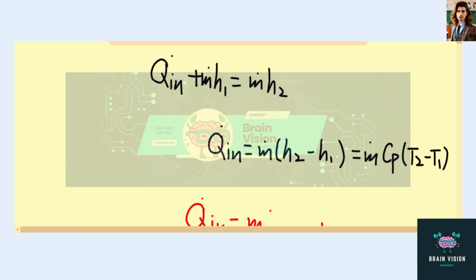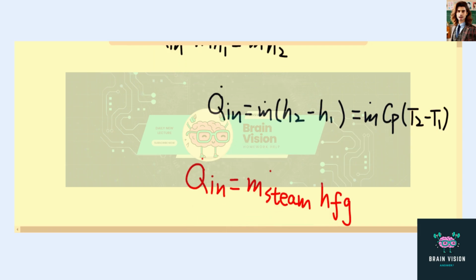And we also know that the rate of heat transfer into the cooling water can be equal to the rate of the condensation of the steam in the condenser multiplied by the heat of vaporization, okay, according to the energy conservation law. Because when heat is transferred to the cooling water, that means the steam is also losing heat from itself since it's transferring to the cooling water, okay? So now we can use, actually this one should be condensation, okay? So M dot condensation.